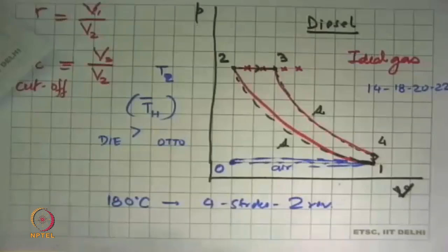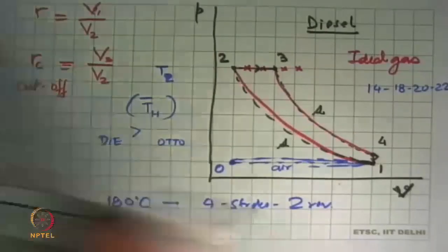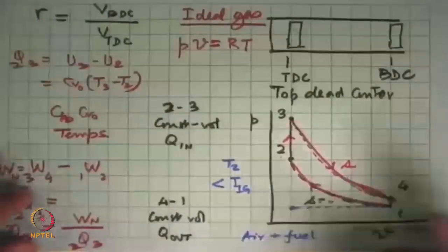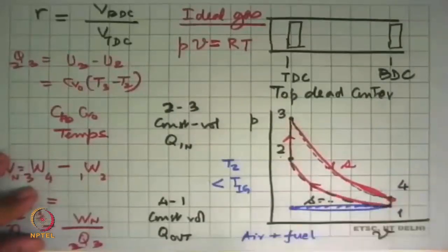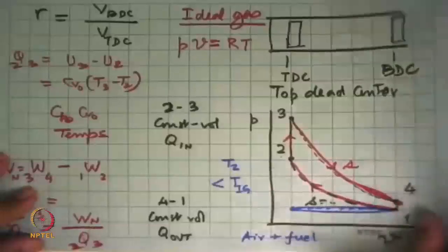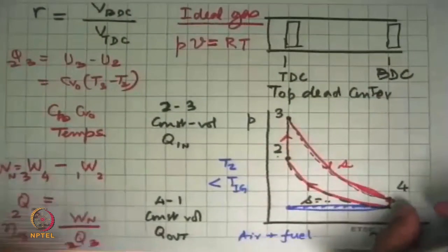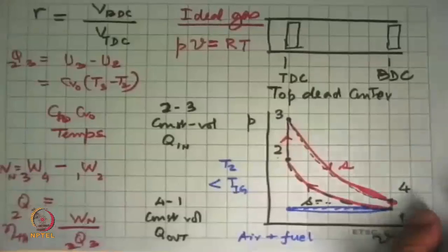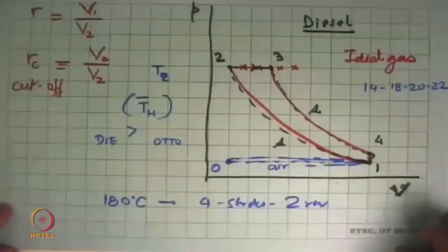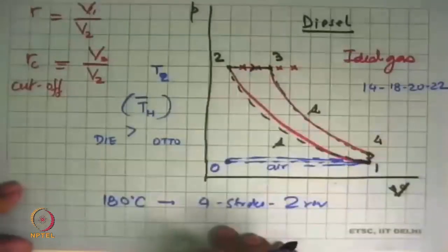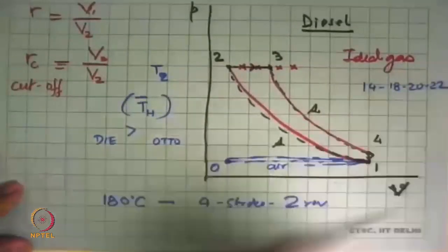There were 2-stroke petrol engines. I won't go into the details of what the problems are. There also you do the same thing. You got 2 more strokes sitting over there. But those are now pretty much on the way out because of the pollution effect and the lower thermal efficiency. But 2-stroke diesels are very much alive in big numbers, and all the big engines are all diesels.